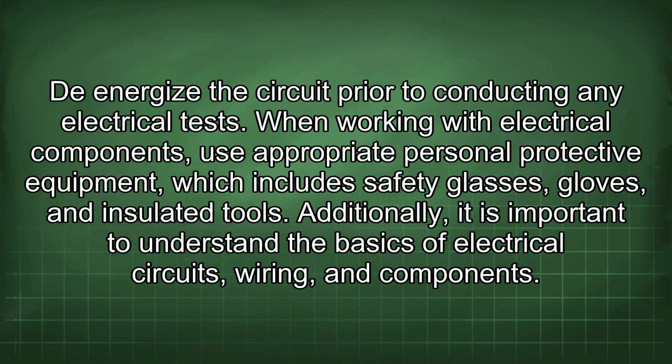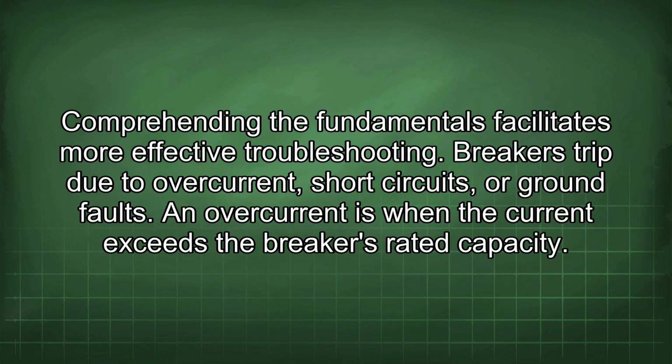When working with electrical components, use appropriate personal protective equipment, which includes safety glasses, gloves, and insulated tools. Additionally, it is important to understand the basics of electrical circuits, wiring, and components. Comprehending the fundamentals facilitates more effective troubleshooting. Breakers trip due to overcurrent, short circuits, or ground faults.